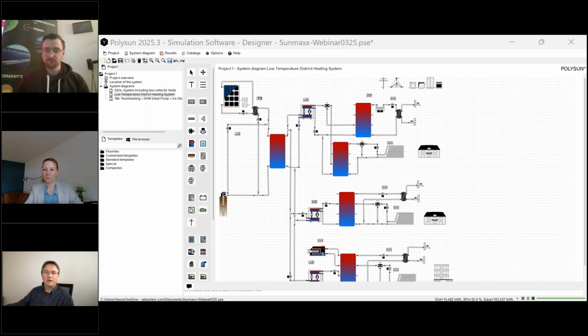And as we were talking now about summer, the next question is concerning winter. So how do you do it in winter? Can the panels freeze? Yeah, the panels can freeze. From the PV module itself, the temperature doesn't matter anyway, so it is tested down to minus 40 degrees, so nothing will happen with the module. But of course, if you extract the heat and we have minus 10, minus 15 degrees, we have a light freezing area on the back side, even possible on the front side.